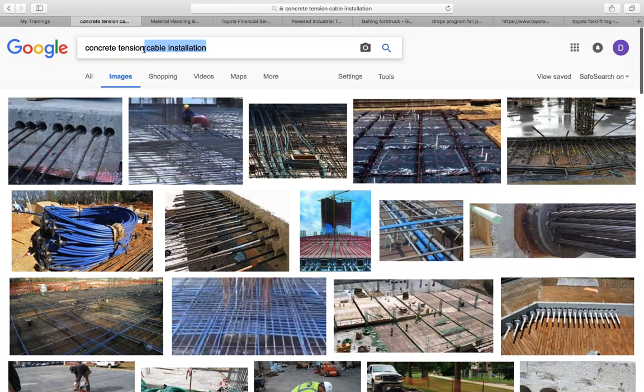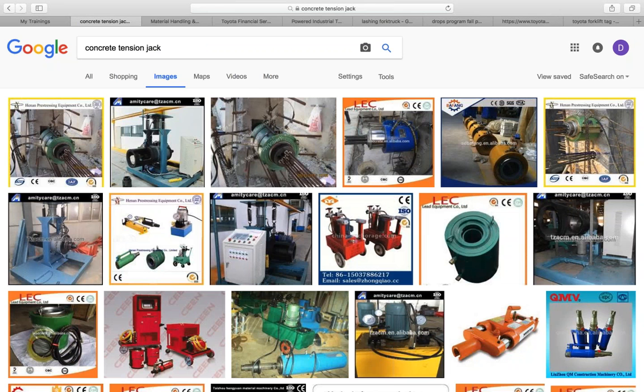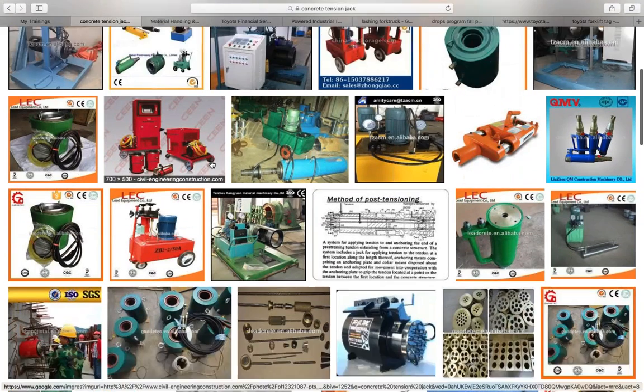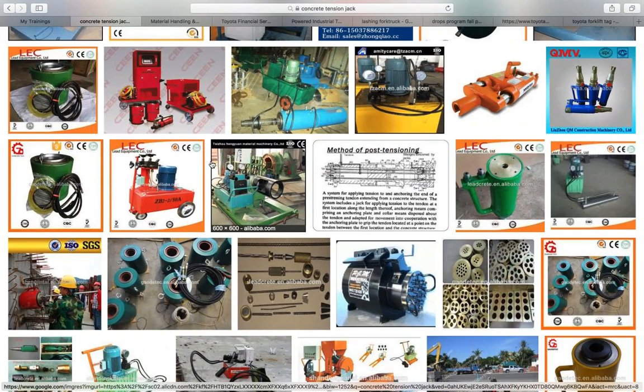So those are all different types of jacks, and that's what I was talking about for anybody who's not familiar with it. Workers aren't permitted behind them. Also, workers aren't permitted underneath any type of concrete buckets or buggies. Appropriate PPE has to be worn at all times.